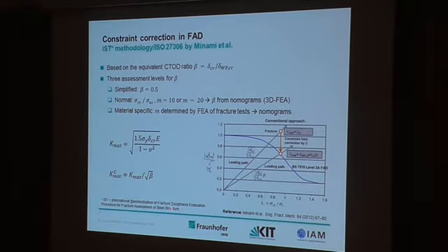It comes from the abbreviation for the project they had in Japan. And this method works in a similar way, and with some differences. They traditionally use the CTOD instead of the stress intensity factor or the J integral, and they have derived their beta factor similar to that in the FITNET approach from finite element analysis, also based on the Weibull stress model. And they have different rules for how to apply this, how to calculate this parameter to avoid, for instance, material testing,